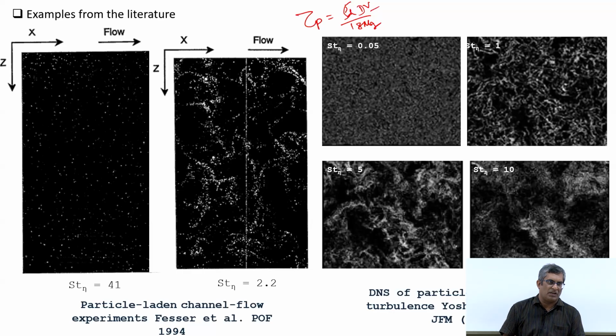So, this is the reason why you cannot capture this in RANS based modeling, and up to some extent in LES modeling, because there we resolve large eddies, but we consider small eddies also, although we are using a model for small eddies without resolving them. So, here you see the DNS simulation. Now, the DNS simulation allows a very systematic investigation here. For example, you can change the Stokes number in whichever way you want, which might be difficult to maintain in the experiment.